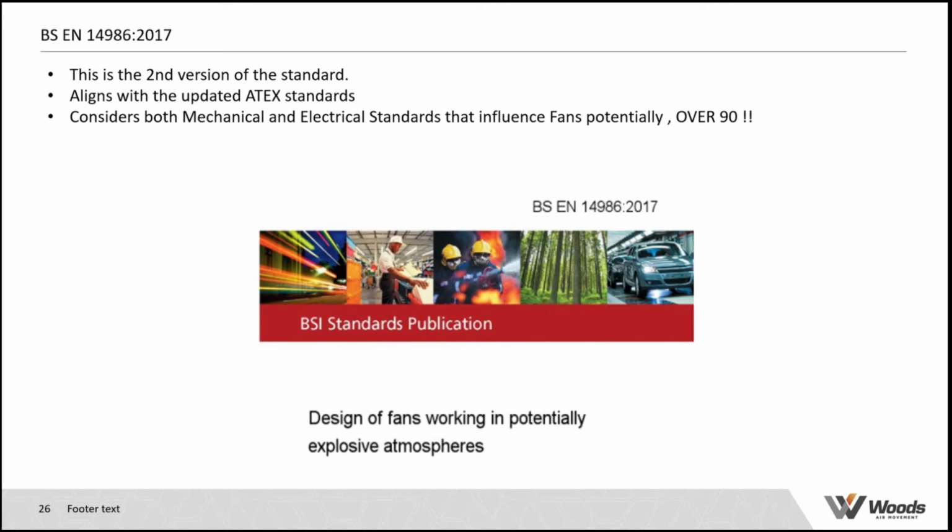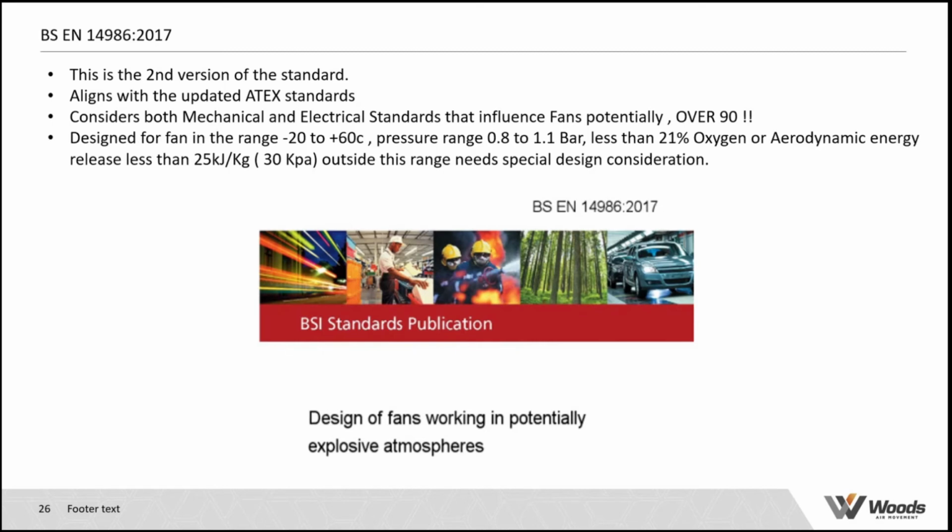What happened is that when the standard was put together, a group of experts, only a few fan people, but there were risk people, there were chemists and experts in the field, put together the standard based upon the risk that they saw and the codes that needed to apply. So the range that this covers is from -20 to plus 60 degrees C. We can go higher if the components are certified higher. Ambient pressure range 0.8 to 1.1 bar, less than 21% oxygen, and basically pressures below 30 kilopascals. That needs special design after that.